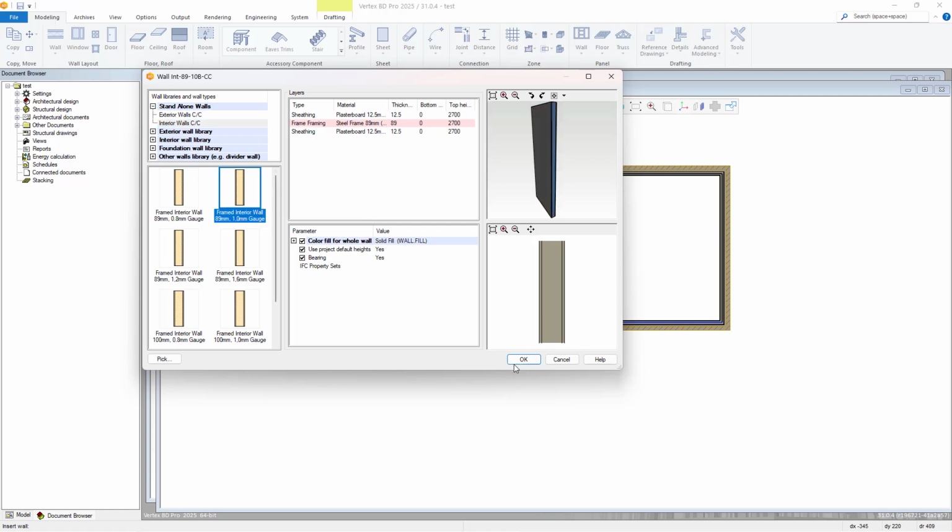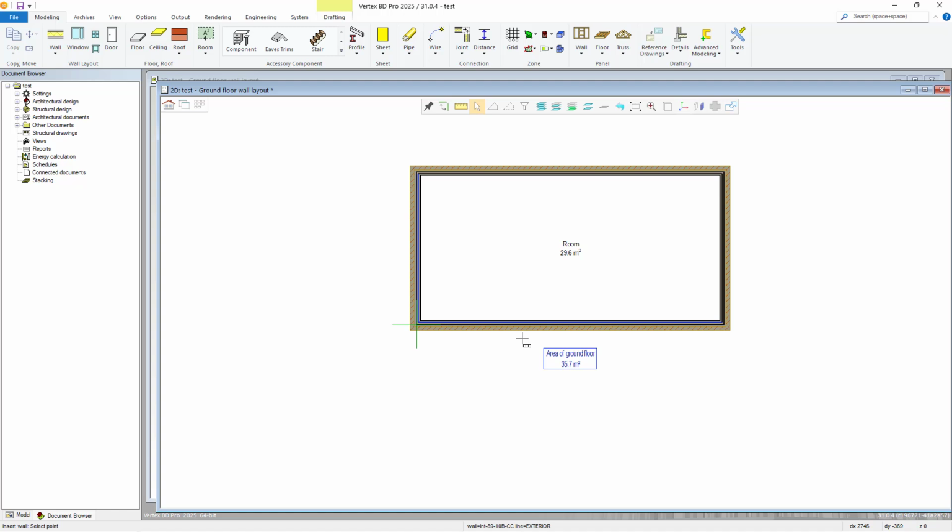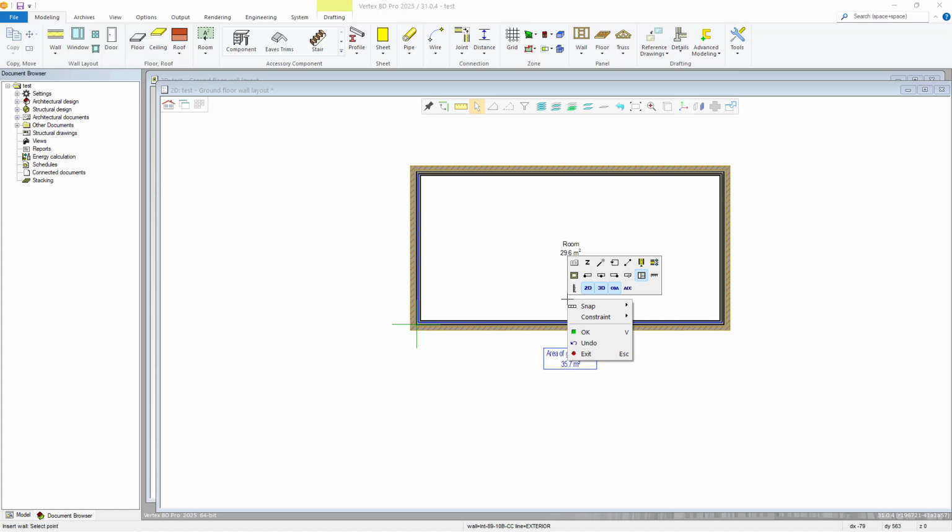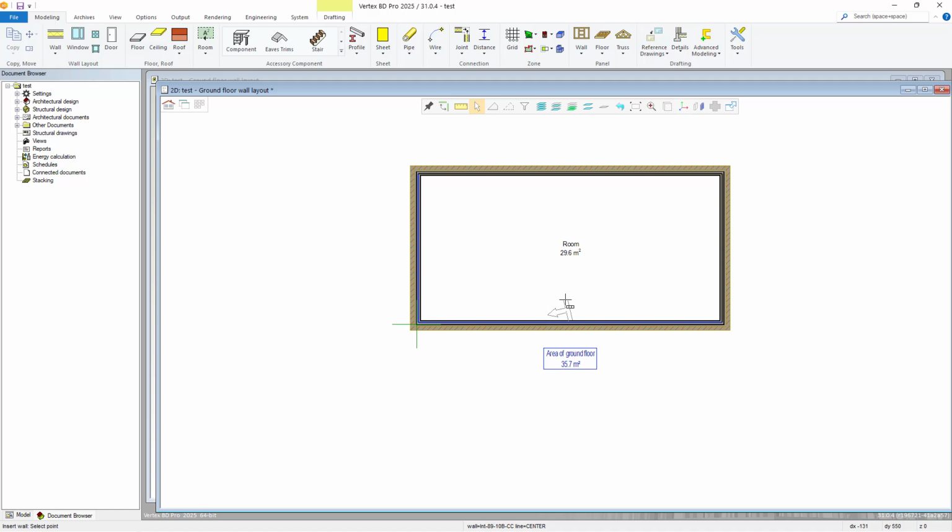We want to place the internal wall in the center of the long wall, hovering over around the yellow triangle in the center. This will appear denoting the center of the wall. We can then click this point to fix the wall there. Due to the wall placement, this will be slightly offset, so we can right-click and go to the contextual menu and then choose the placement wall middle icon. The wall will shift. We can then lock it in the Y-axis with the I key, typing in 2000 and hitting enter to make the wall 2 meters long.